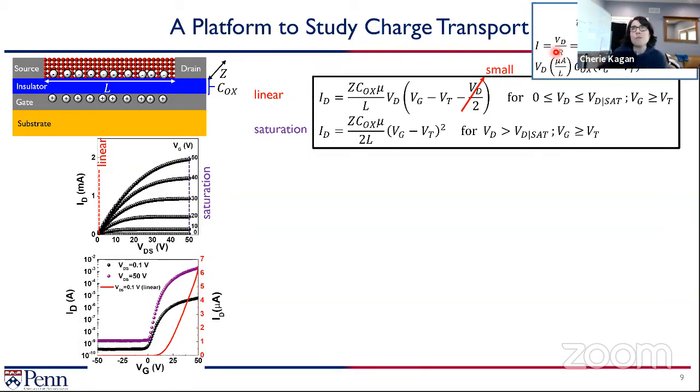You know Ohm's law, which just says voltage equals current times resistance. So if I flip that around, I can say current is voltage over resistance. And then resistance depends on the resistivity, or inversely the conductivity of the material, and on geometric parameters like the length as well as the area of the film. And if I ask what's conductivity, well, that just depends on mobility and the carrier concentration. So if I start with Ohm's law, you can start to see where this